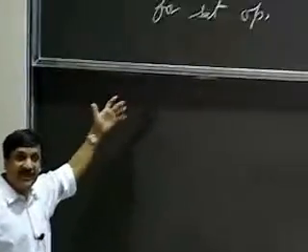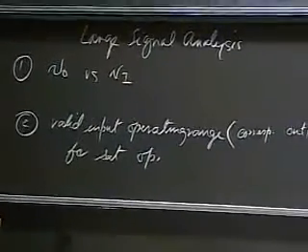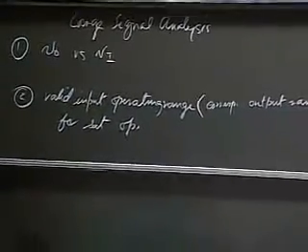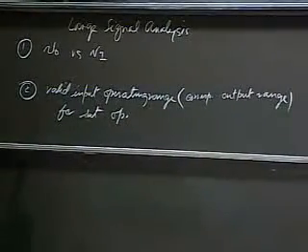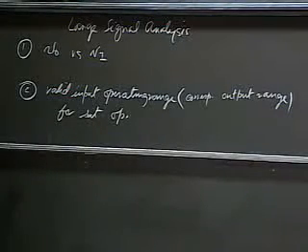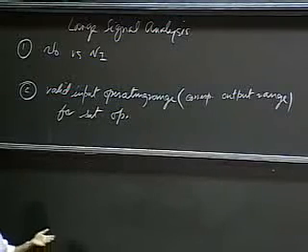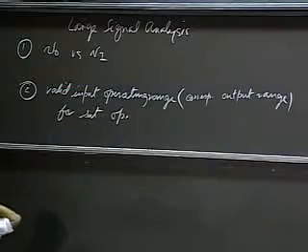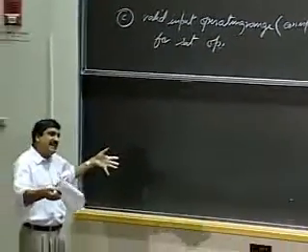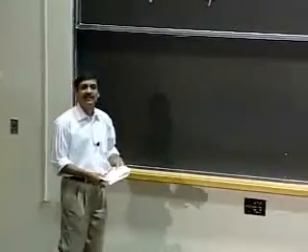So what we're saying here is that if I'm careful with how I apply Vi for a given value of RL and Vs, and for a given choice of my MOS transistor, then I can stay within saturation, provided I select my input voltages carefully. And the analysis we will go through today will figure out what that range of input voltages is. Again, I will use the MOSFET amplifier as a motivating example, but in general, large signal analysis would apply to any other circuit as well.